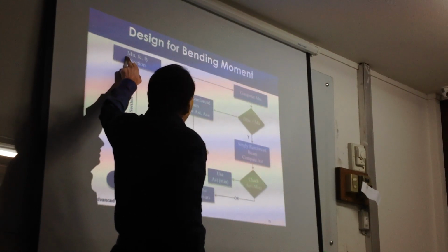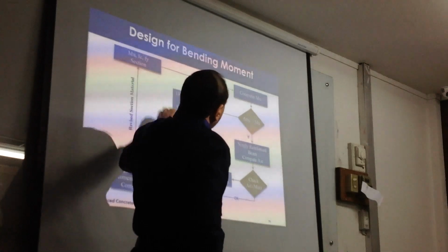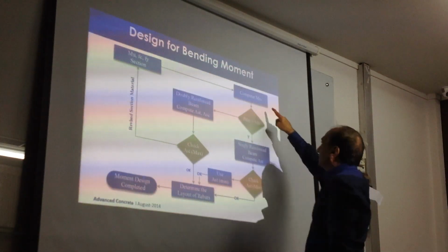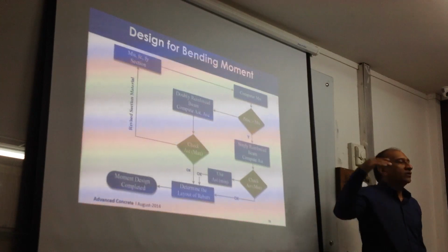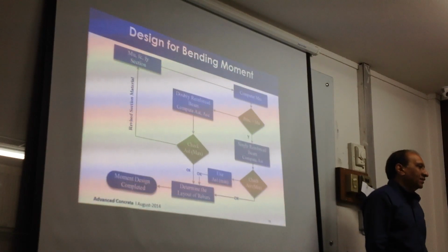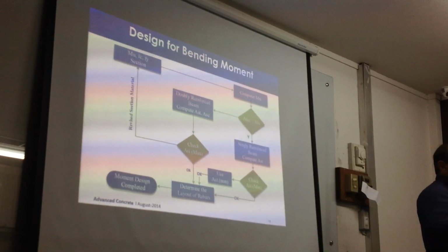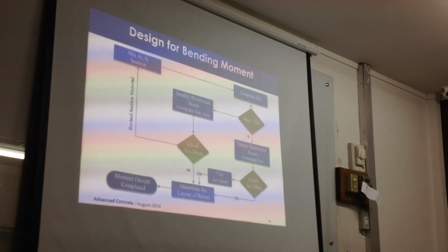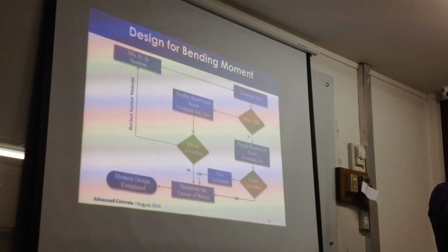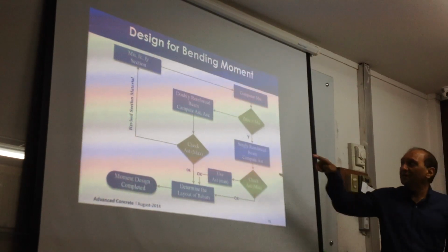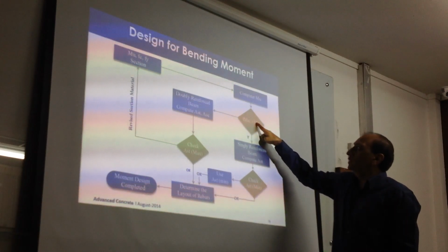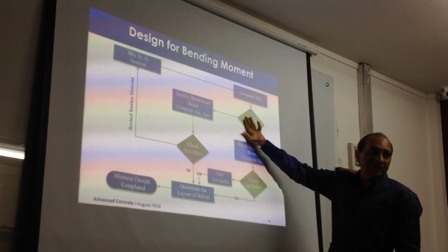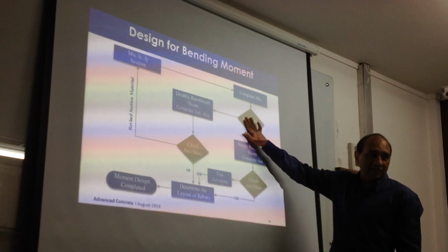Okay, we take one moment. Calculate MRC, calculate the cracking moment, I'm sorry, not cracking moment, moment of resistance of the concrete of the section based on the balance condition, reduced by the factor 0.75 balance, something like that. If MRC is more than MU, that means the capacity of the section, concrete section capacity is already enough.